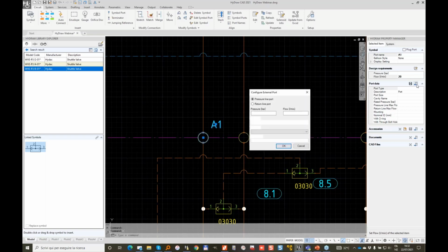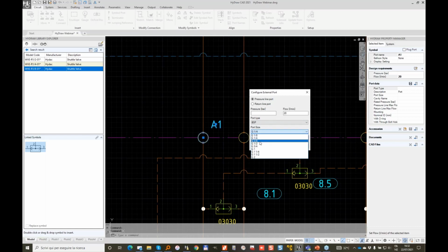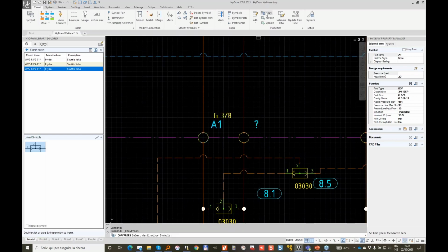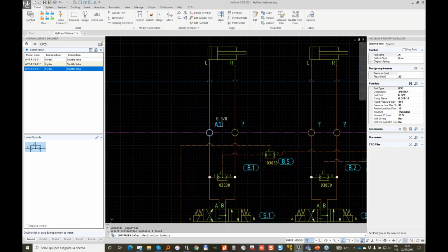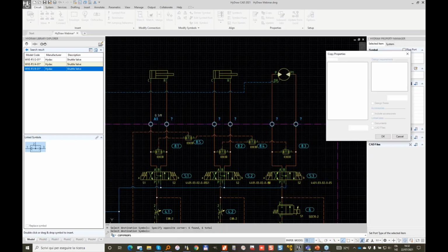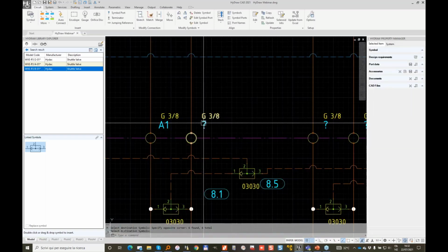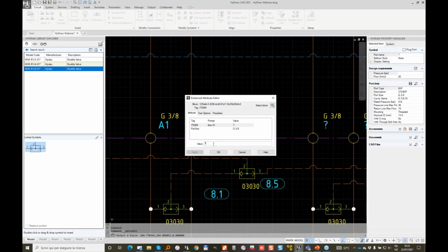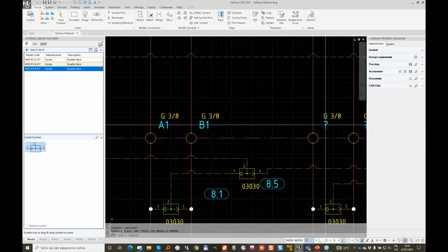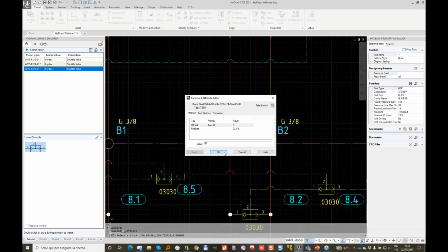Now let's look at what is the recommendation for 20 liters per minute. My system is saying 1x4 is enough. That may not be the case for me. I need a slightly larger one, 3x8. We can copy size from one port to another. Let's say that in these items, we want to copy all the sizes. So A1, to do it faster, you can just double click and type the item ID B1, double click A2, and double click B2.